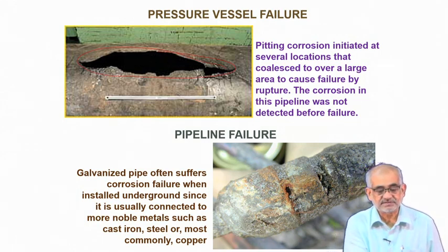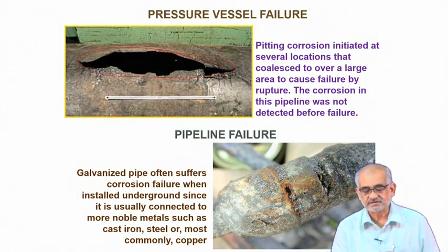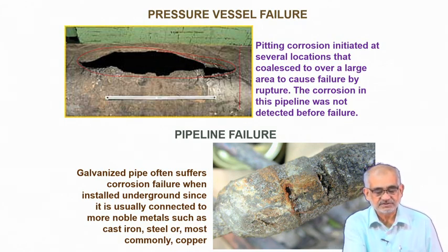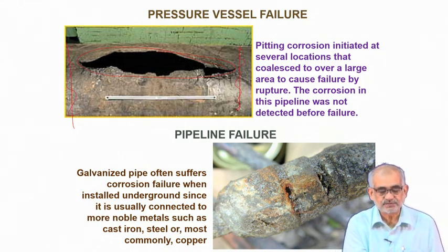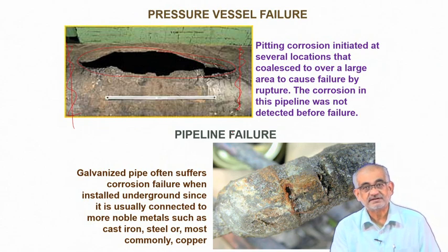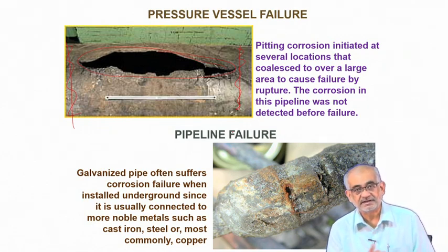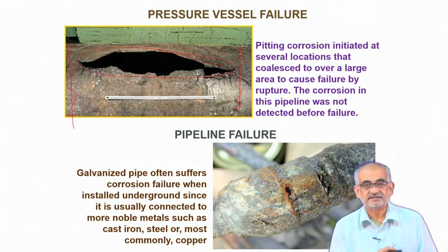So these ruptures are very common in the pressure vessel tubes, and when such a rupture happens, you either chop off from these two ends and bring in another piece of tube and then join by welding at these two spots. Then these welding joints become another possible region of future failure. So one has to be careful about them.